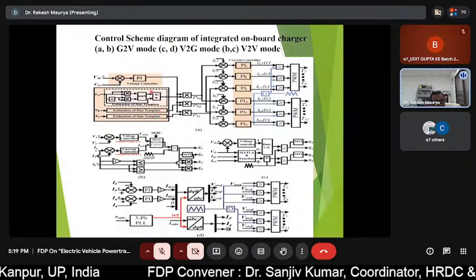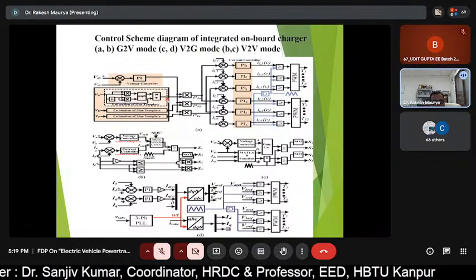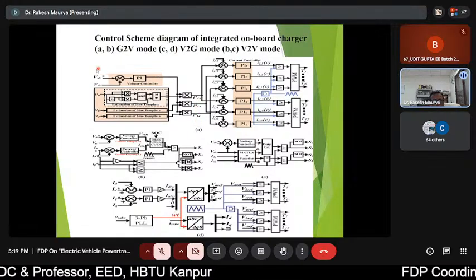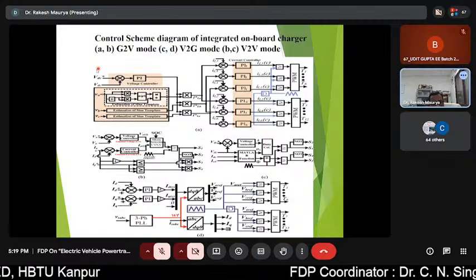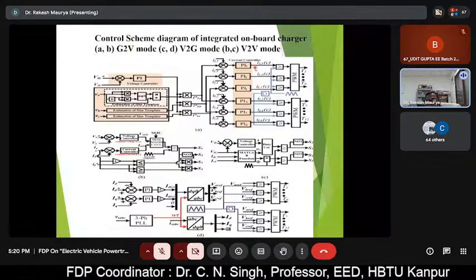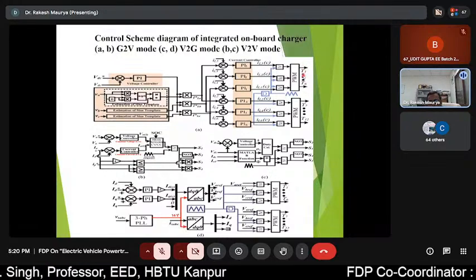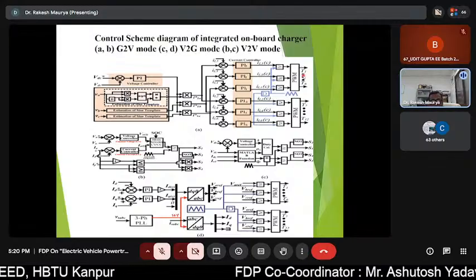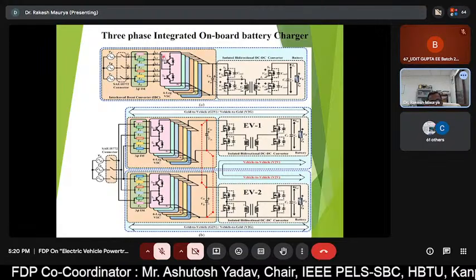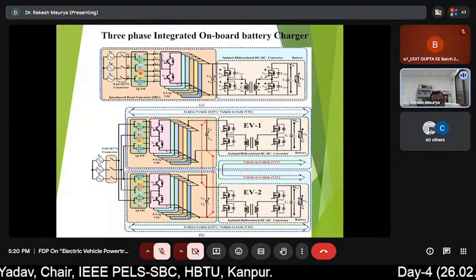Here we can use the voltage sense template of phase A, phase B, phase C, multiplying to get each phase current. So this control is called a boost PFC converter, and then it is compared with the individual motor winding current, and then it is passed through the PI controller to generate the reference current. So all the six legs can be powered through a simple three-phase PWM rectifier. It's a very common control, and one can ask questions here also.